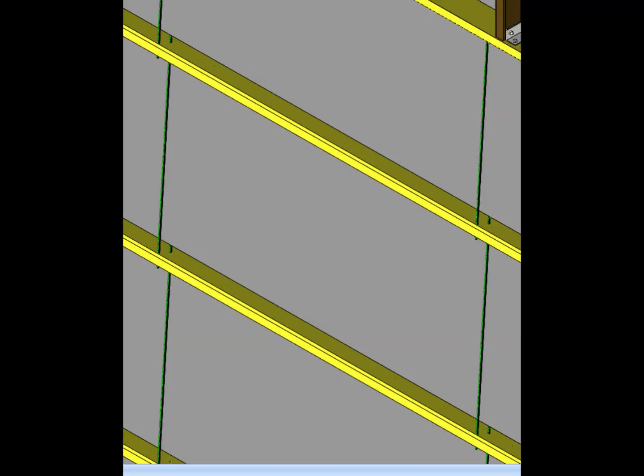Now, let us compare what we are seeing here with the concept of a sag rod. A sag rod is a secondary member used in conjunction with the framing system to provide support and stability to the associated secondary framing members. In this side wall arrangement, the sag rods are positioned between the horizontal wall members, creating an interconnected framing arrangement.